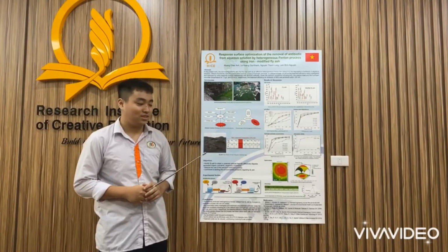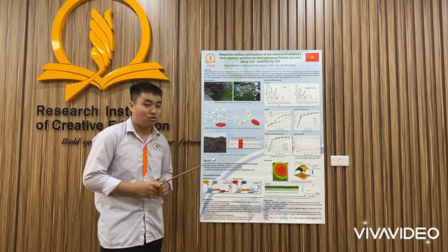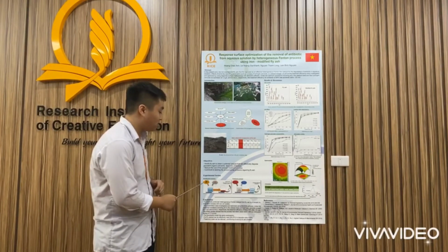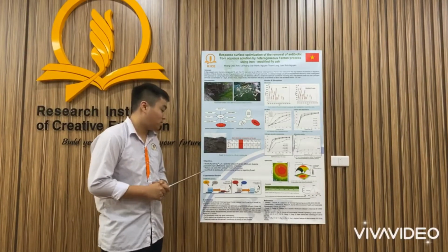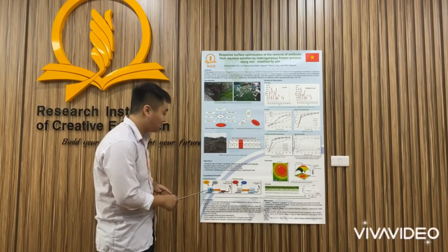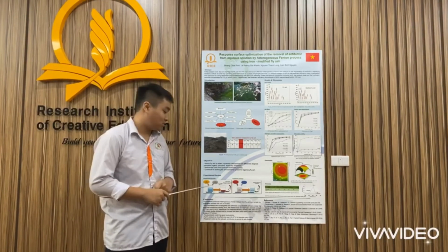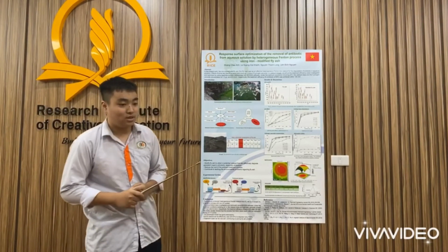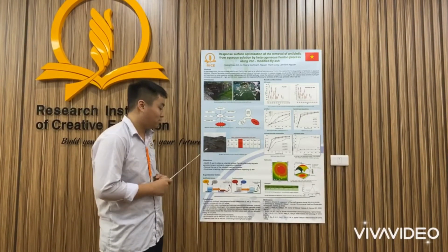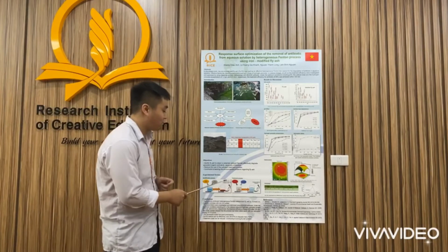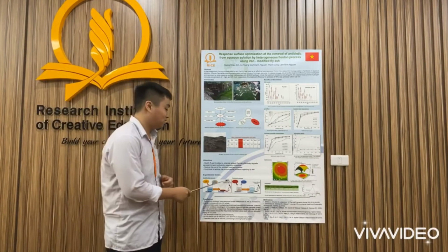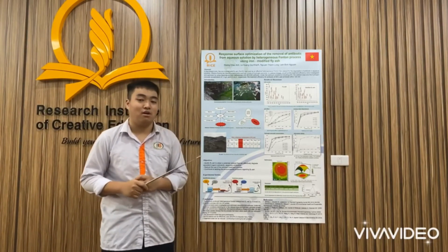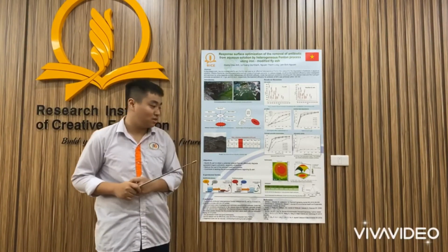For this purpose, we designed the experiment as follows. 1. Modification of fly ash. 10 gram fly ash and 5 gram iron salt were added into 20 ml water. The mixture was then mixed and heated to 100 degrees C for removing water. The obtained solid was processed at 600 degrees C for 4 hours to obtain the catalyst, iron and fly ash, which will be used for degradation of antibiotic and other organic pollutants.